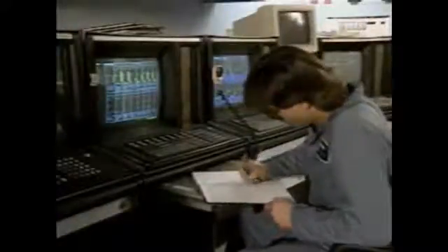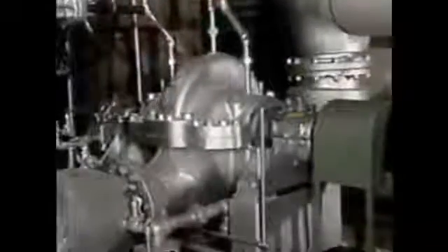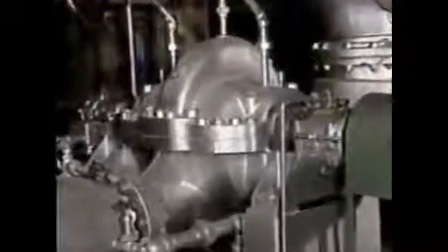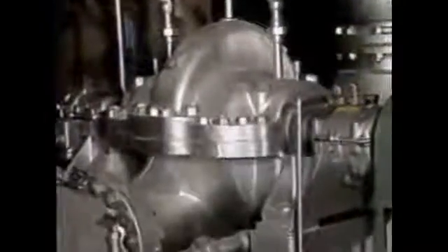When a pump is selected, it is chosen for a specific combination of head and flow. Head and flow are also examined to determine how well the pumps in a plant are performing. As an operator, your main concern in determining a pump's performance is whether or not the pump is supplying the correct pressure and flow. The values for proper pressure and flow are often based on the pump's design characteristics.